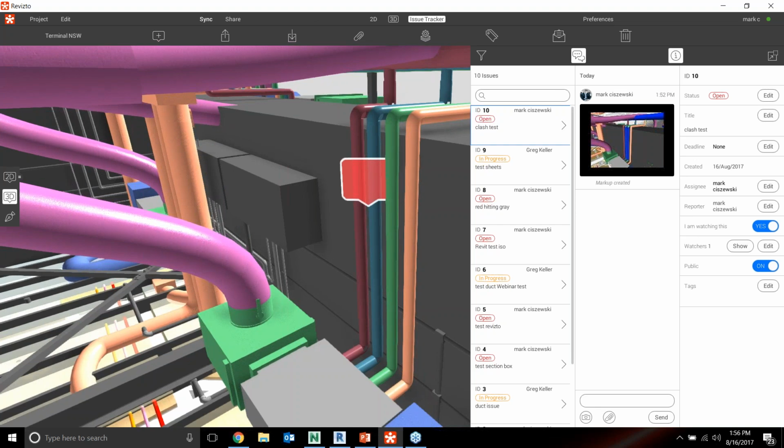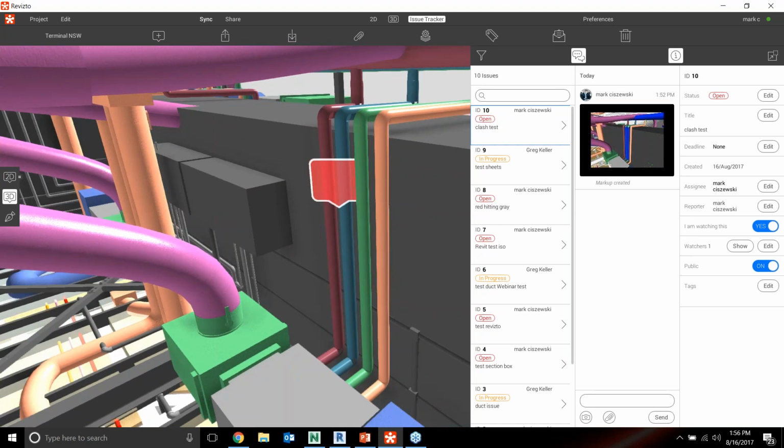So if the screenshot in Navisworks or the screenshot in Revizto doesn't line up with the 3D model, I know if the project shifts, if the project survey point or true north or something shifted with the coordinates, sometimes that can throw it off. In our next release, we're going to be supporting pure coordinates, 0 to 0, origin to origin, etc. So there's a number of different benefits to our 4.5 release.